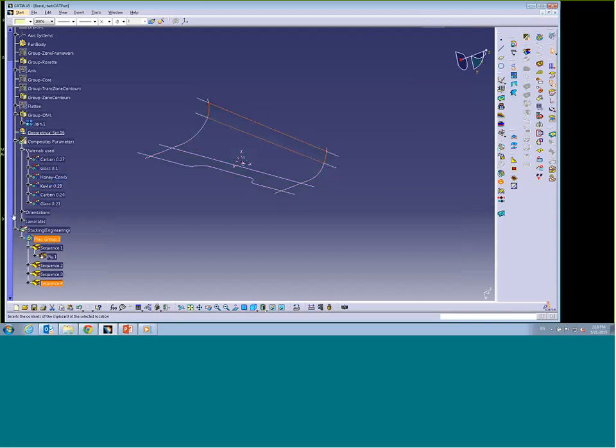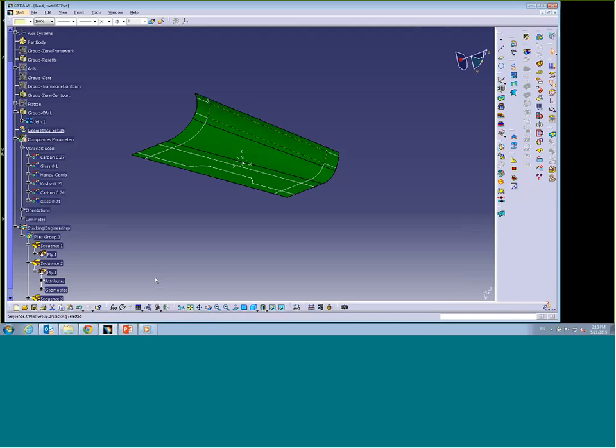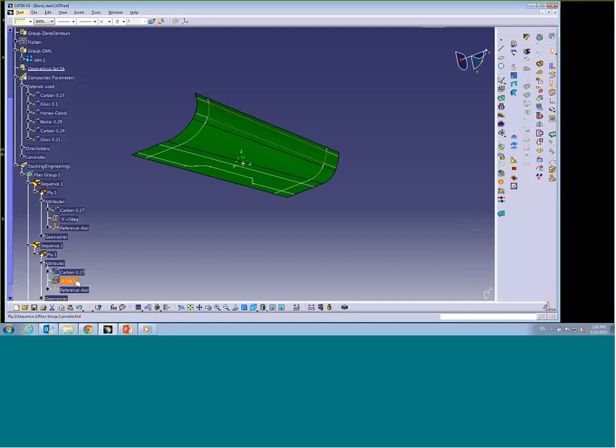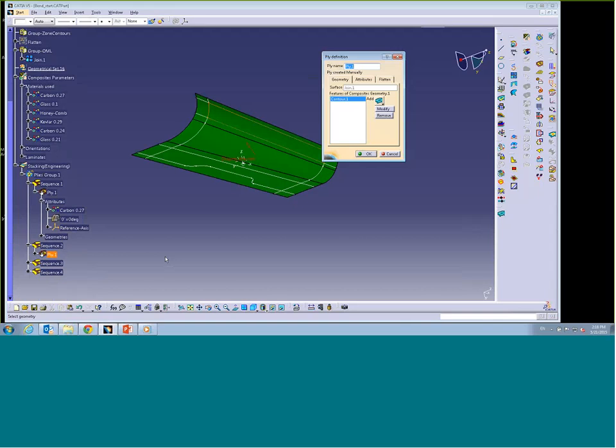Okay. So it seems to be pretty quick, and actually, by the way, at this stage I can change material. For instance, you see ply 1 shows 0 degree orientation. Let's say my second ply I want to have at 90 degree, just double click ply 1, go to attributes, and instead of 0, I'll just change it.